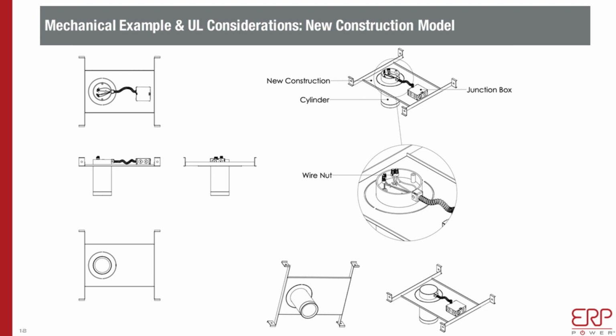All we want to show is how you do the mounting and isolation and conduit. Notice that, again, you don't need to have the J-box, but a lot of our large customers told us that, yes, electrically and by code, we don't need it, but electricians and installers are used to doing installations with the J-box, and that is why, although it is not needed, they put it in there, because they're not going to be able to train thousands of electrical technicians that all their life have installed fixtures with a J-box. So that is the reason that it's there.